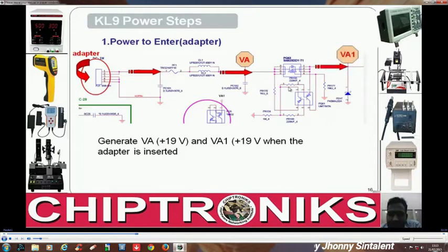Now this is a P channel MOSFET. How do I know that this is a P channel MOSFET? As I have explained, a MOSFET in which the arrow is outside is a P channel. But normally in a P channel MOSFET, we observe current flows from source to drain, right? Not from drain to source, but source to drain.